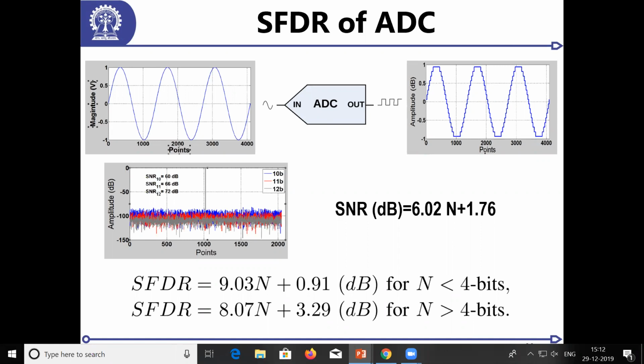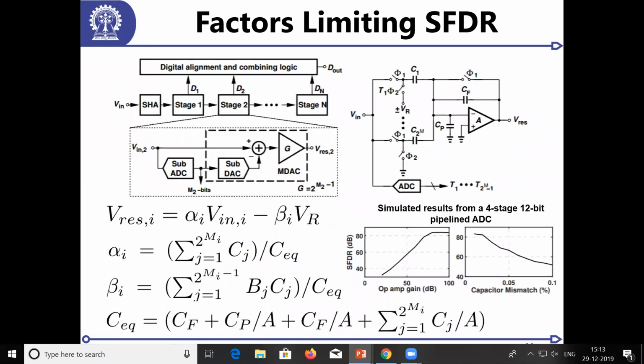I can also add random noise and get this performance. So if I add noise to any signal in a clever fashion, it can give me better and better resolution. Adding noise to a signal in a clever fashion is called dithering, and dithering can give us huge enhancement in the resolution. This is a very simple example.